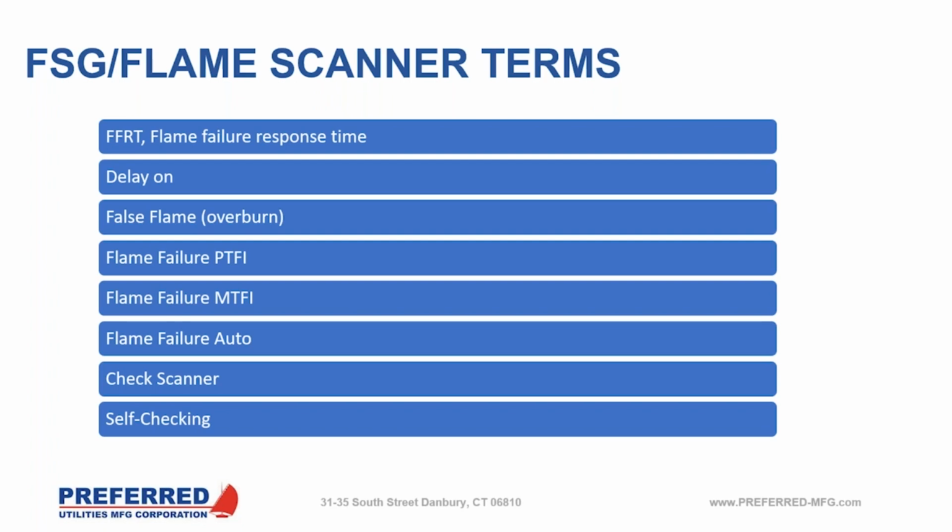And so when you have an issue and a flame failure, make sure that you know what that range is. And hopefully someone took some notes when they actually started up the burner originally, and they recorded what those flame signals were at pilot and at main flame, and then across the firing rate range. If those notes are there, that's extremely valuable for someone that's trying to troubleshoot a problem.